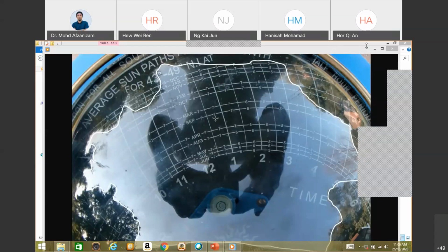Now the numbers that you see in here are every half an hour, basically going from the beginning of the day to the end of the solar day. You add up those numbers, and we come out to 100%. You had no shading problems at all. Clearly, we have trees around my house, so I have to subtract those numbers out. The basic idea is to take these numbers that are shown in clear sky, add those up, and that'll tell you the percent of the time that the sun is shining, not being obstructed by trees or any other obstacles. So that's the basic idea.